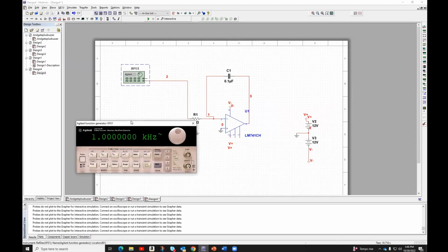And it's a sine wave, so then I'm going to look at what happens to my output when I run that circuit. To do that, I'm going to select my scope again, and hook up my channel 1 to the input function generator, and channel 2 to my output.